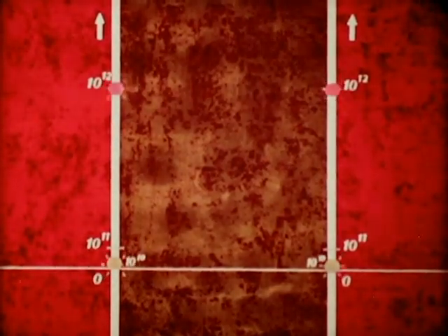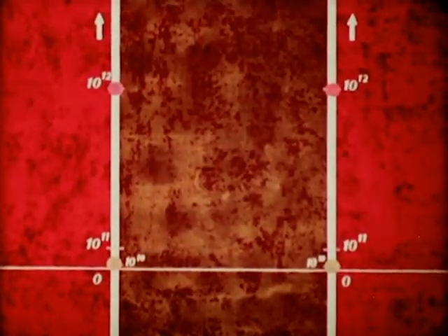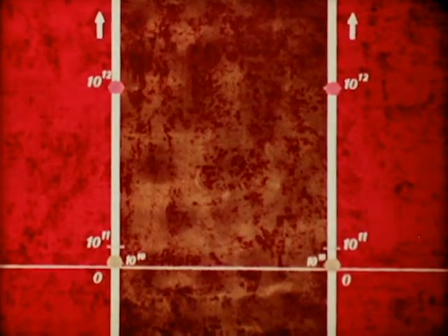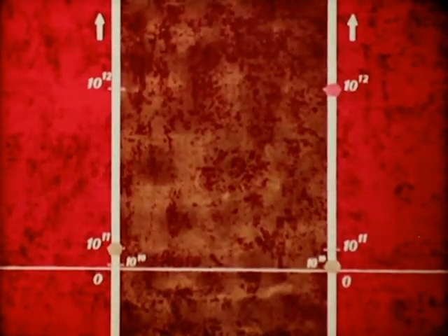Holes then diffuse from the emitter into the base, flow on to the collector, and are absorbed by it. The minority concentrations will increase at the emitter base junction and decrease at the collector base junction.